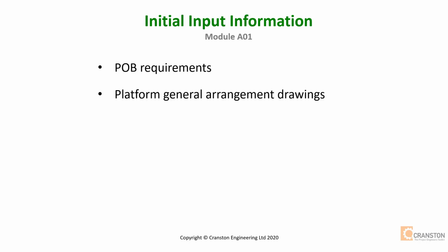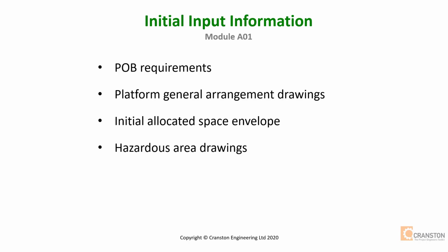We'll have the existing platform general arrangement drawings. We'll have the initial allocated space envelope for the accommodation. We'll require the hazardous area drawing showing the relative location and distances to hazardous areas. And finally the structural integrity model, which will require updating with the proposed accommodation loadings.